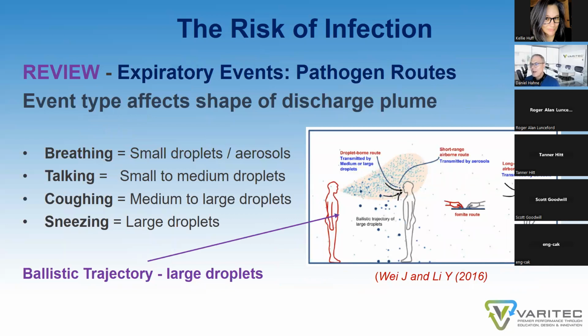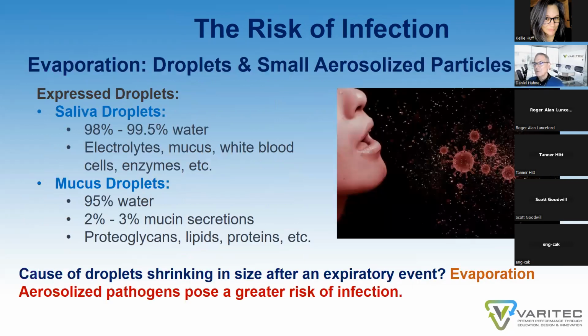So if we look at how those droplets are dispersed and their rate of evaporation, if it's high, it will allow for desiccated viruses to be released into the atmosphere where they will free float in the space and become an infectious agent for other occupants. So you want to reduce the rate of evaporation within the space of those droplets so that they remain large, and due to the force of gravity will drop out of the air rapidly. So humidity does impact the release rate of viruses in a desiccated state into the air.